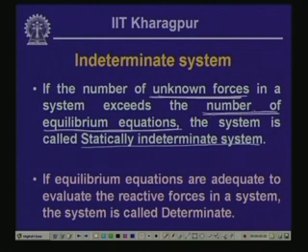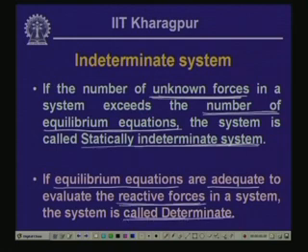We have seen what is meant by equilibrium equations, and for the solution of such systems we have seen that we need additional criteria to be brought in so that we can evaluate the unknown forces. And the way it differs from the determinate system is that if the equilibrium equations are adequate to evaluate the reactive forces or the internal forces, we call those kind of systems determinate ones, and this distinguishes between the indeterminate system and the determinate system.